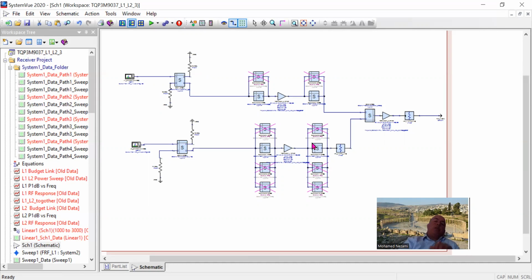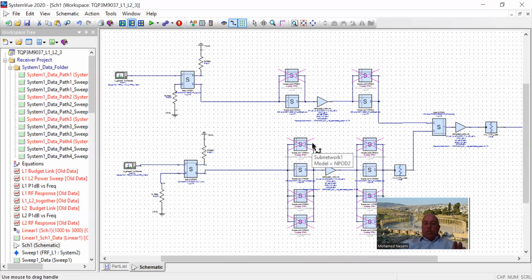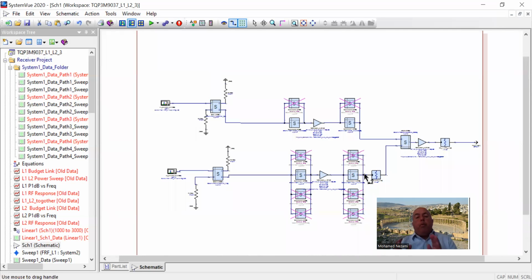But personally, what I'm going to do is go into Altium or Cadence and do the schematics first, then do the layout, taking the precautions needed on the filters. On all of these components, I would use exactly what the manufacturer's evaluation board does, similar footprints and similar layout techniques, because they made the device, they experimented with it, they know how it works, and they know what's best for it. And then I would import the board into HFSS or into RFPro to do